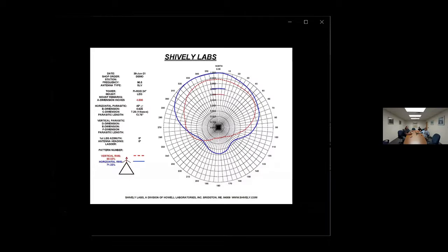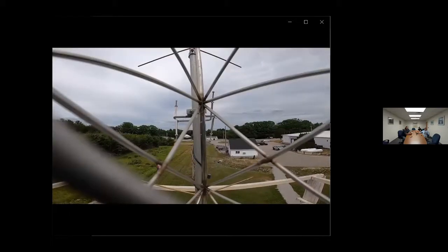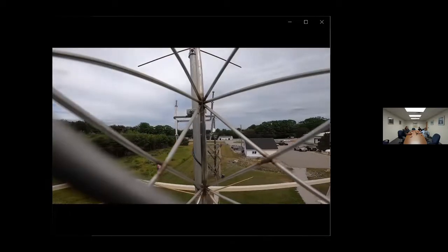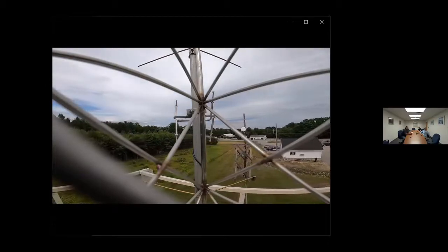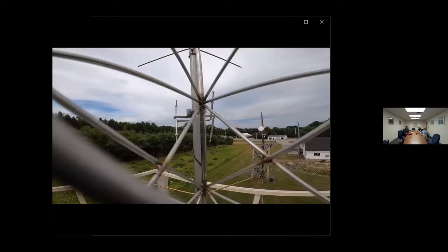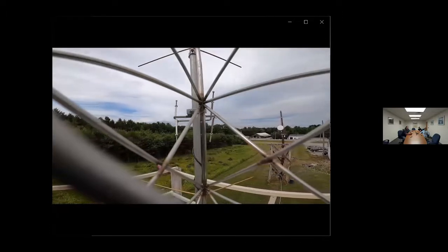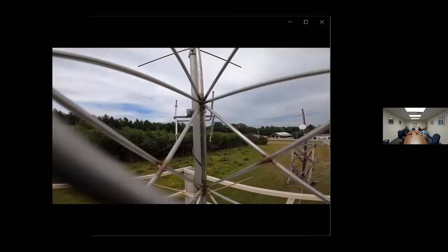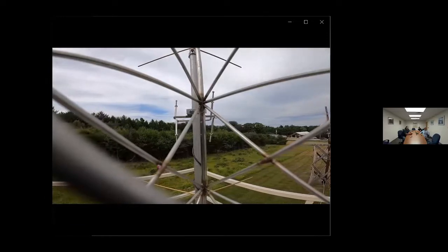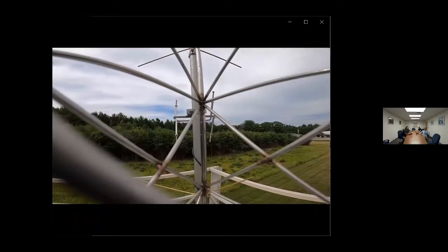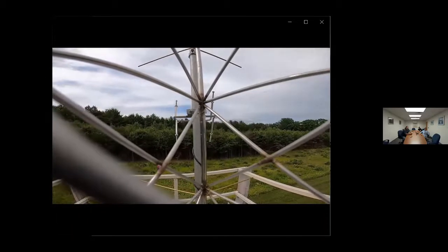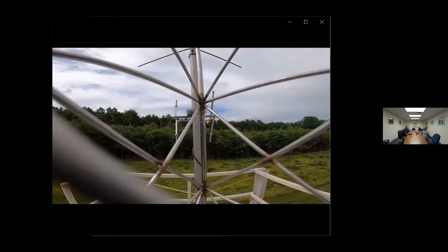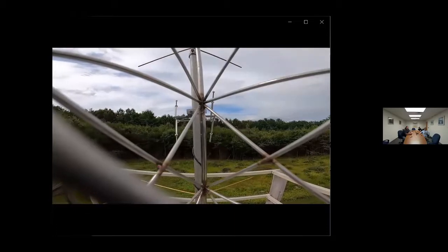What I want to do now is do some focusing. So there was a very wide half power beamwidth from that last one and a bit of backward radiation that I'll try to get rid of for demonstration purposes. What I'll do to accomplish this is flip the paras forward. This is for extreme DAs and something that needs a lot of focus. I don't do it a lot, but it's a neat trick if you need to shrink your pattern down to fit inside of something.